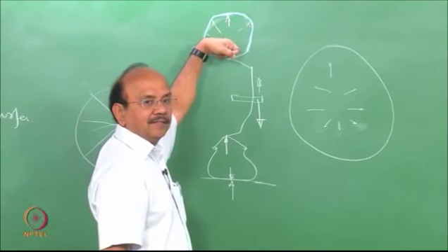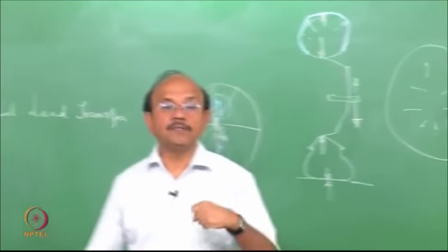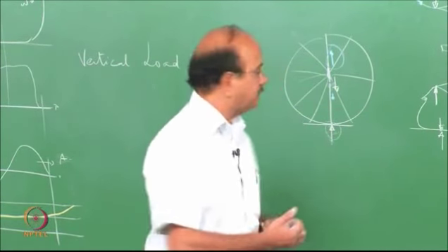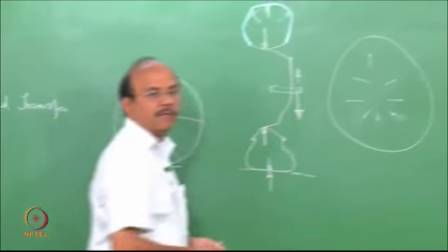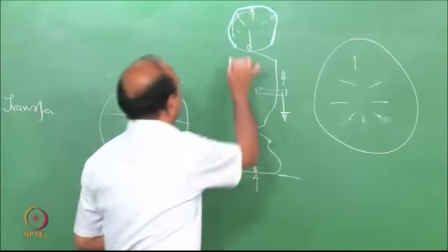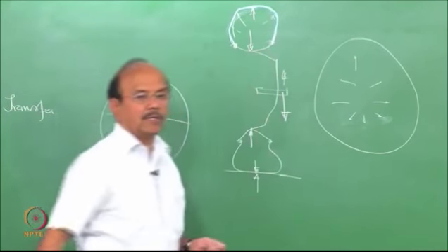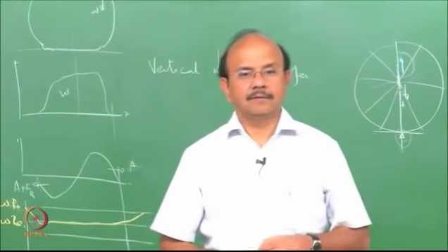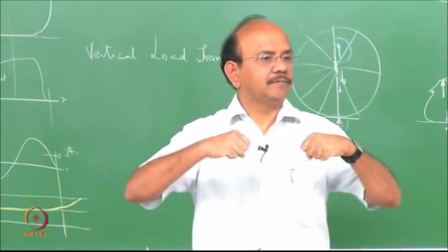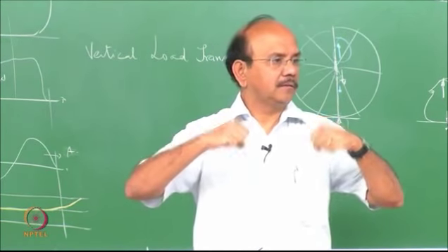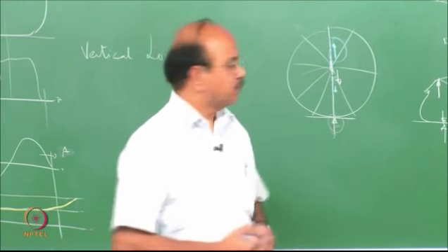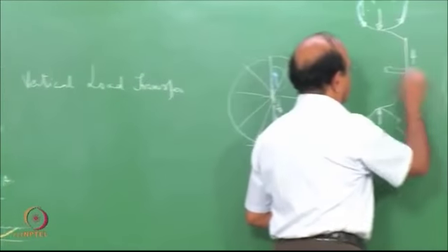Again, as in your bicycle wheel, a passenger car tire or a truck tire or whatever it is is actually hanged from the top. It is not supported from the bottom. So the whole load actually goes through the sidewall onto the most important component called the bead, which transmits it to the rim, and that gives the force for the rim to support the load.